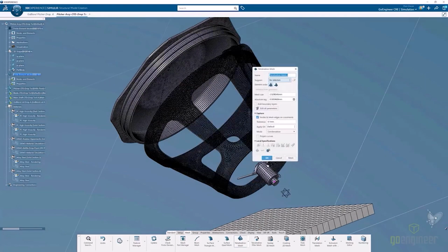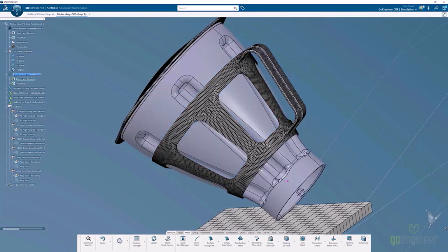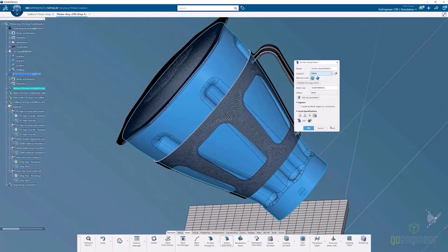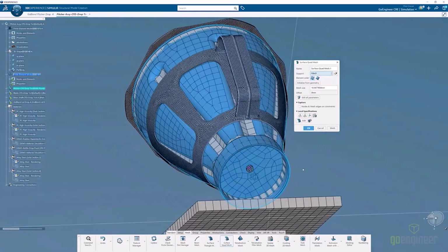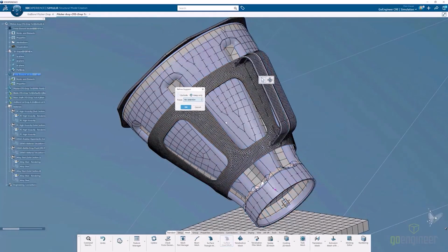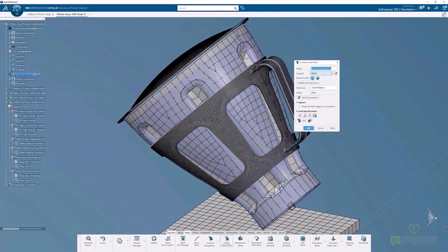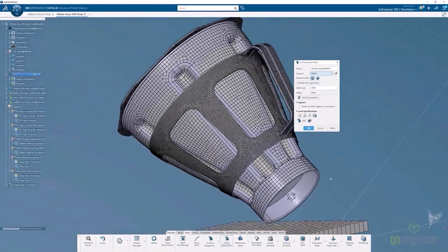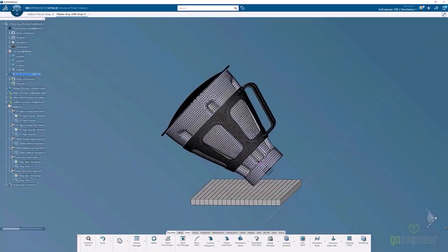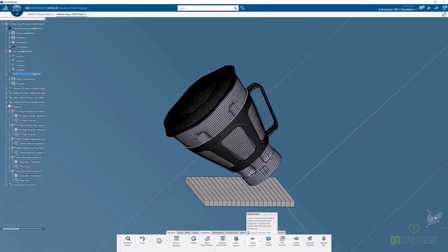The pitcher is going to be fairly coarse, not as refined as the rest, but we're going to get a mesh on that here as well. And then he also added a ground object below as well. So we can see he's kind of setting these up. He's going to go through and manipulate the overall mesh size. He's actually doing a hex dominant mesh, something that's very specific to 3D Experience and Abaqus, which is actually pretty nice. Now, from there, he generated the mesh.